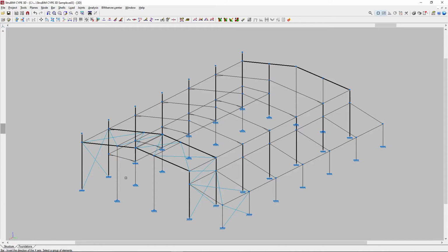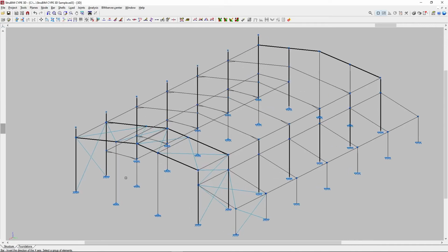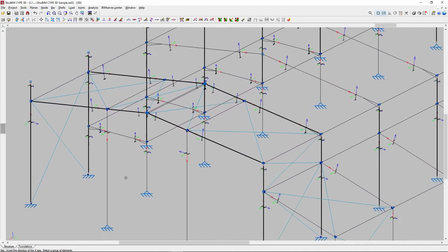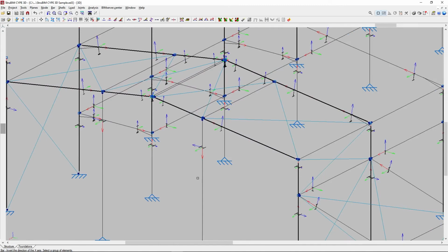The local x-axis is shown in red on each of the bars of the model when we approach them. If we have described fixity coefficients or introduced loads, the program will automatically modify their data so they are not altered after inverting the direction of the axis.